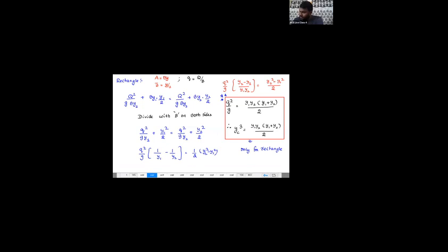Okay, fine. So this equation is not for the alternate depth. This is for the conjugate depth, and it is going to be similar to that equation. Don't get confused. The similarities between the specific energy and specific force are very high, so that's why I'm comparing those things. Now further, this is not the end.